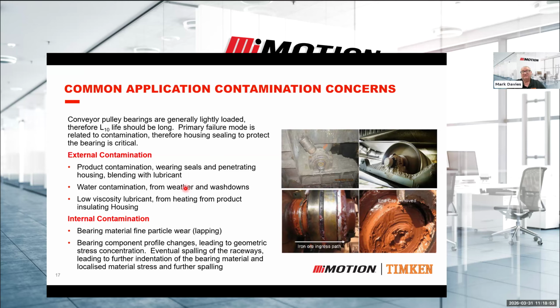But the main thing that kills conveyor bearings, conveyor pulley bearings, is contamination. Almost every mine site and quarry will do some sort of washdown procedure, which is part of their housekeeping to keep the plant clean and wash all this dust off. They quite commonly do push water into the seals and push contaminated products in. So very fine rock dust, coal dust, any type of fine powder gets pushed in through the seals.